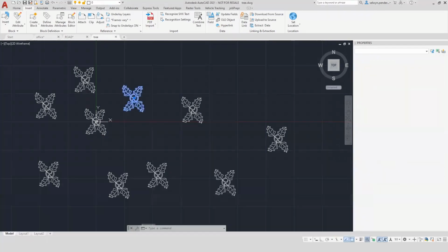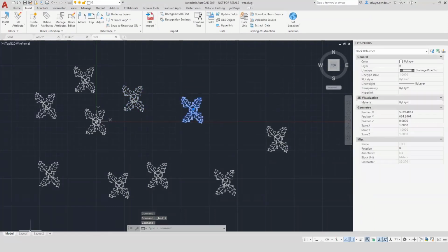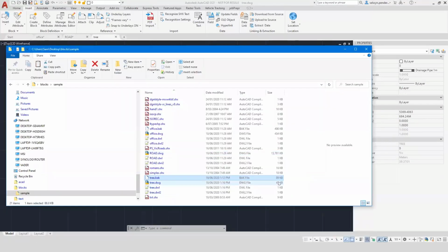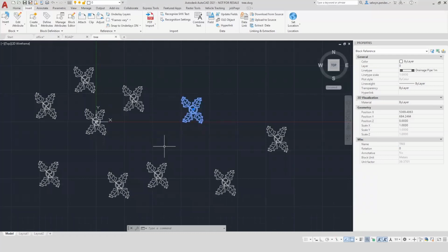So that's a single object, and these are all single objects, and therefore the size of the drawing signifies the use of blocks. So if you've got really complex drawings that have a lot of repetitive objects in them, convert them into blocks. It's an easy task to do, and you'll find that your load times and things will be a bit faster because it's only interrogating the insert table in the drawing database, and it's just grabbing the block reference from there and duplicating it through.